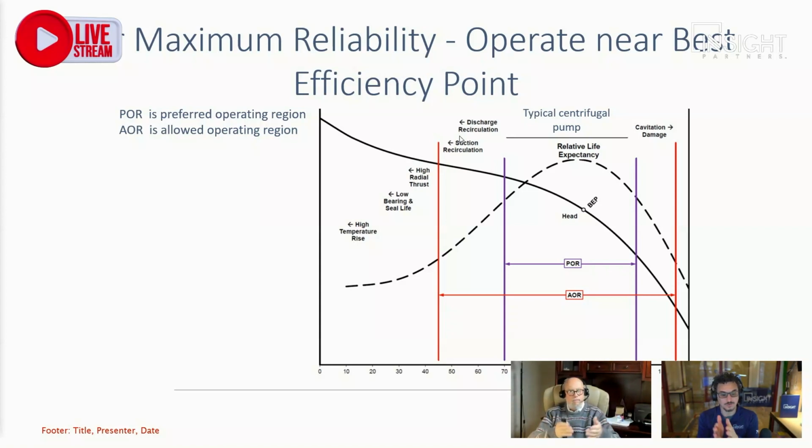So why are many pumps not selected like that, in that range? The vast majority of pumps are selected for best efficiency point at design point, because that's what we did for years and years and years, because that's the way we design constant speed systems or constant flow systems.